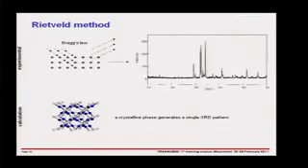And for this reason, X-ray diffraction has really advanced considerably with the Rietveld method. Now, the idea of the Rietveld method is very simple. You have, on the one hand, your experimental pattern, and on the other hand, you make a calculation. You know the crystal structures of every phase that's present. You use that crystal structure with the structure factor to calculate the pattern, and then you compare the two. So this is quite a simple idea.